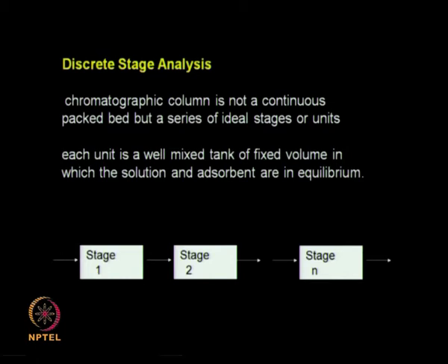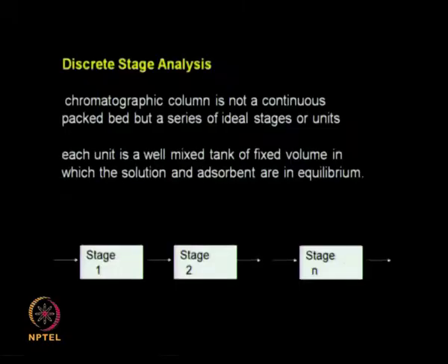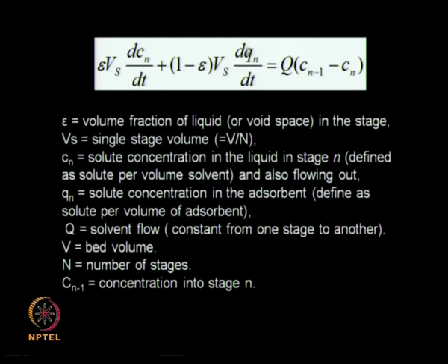So you just have a mass balance, and then after that we assumed a linear adsorption type of isotherm. That means the Q, that is the amount of solute adsorbed in the stationary phase, is in equilibrium with the solute present in the continuous phase in a linear manner. So Q is equal to Kc, that is what we assumed. When you do that, we end up with this type of differential equation. Although this equation looks very complicated, it is not so actually.